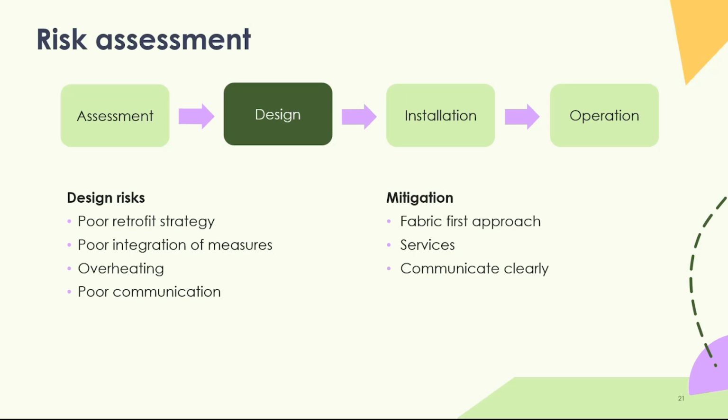In terms of the design risk, then there's a number of risks here that can come into play. So things like poor retrofit strategy. So when something isn't fabric first, which is a principle, not dogma, by the way. Having inappropriate services installed, no or poor ventilation strategy, poor moisture risk management, and over reliance on technology or complicated systems and controls that people are just not equipped to use effectively, or don't have the time or inclination to learn how to use effectively as well.